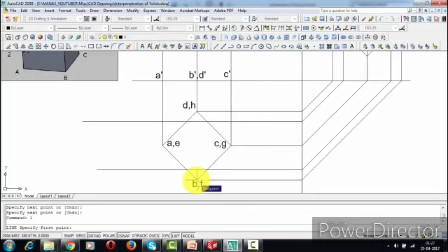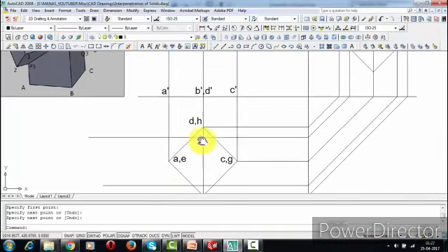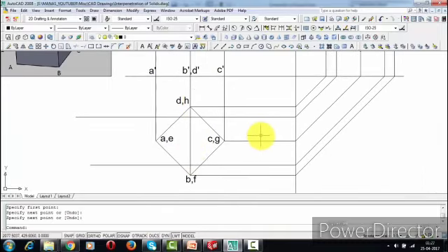Now, what to do now? Something has to be done. Randomly, I'm going to be drawing a line somewhere in the middle. Now, the horizontal prism that we have here has an axis length of 100 millimeters. So I've taken this mid line, and towards the right we're going to draw a 50 millimeter long line. Towards its left we're again going to draw a 50 millimeter long line, so that the overall length works out as 100 millimeters. So let's do that. I'm going to start from here. This is going to be 50.